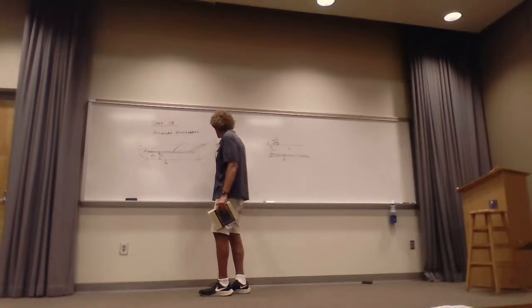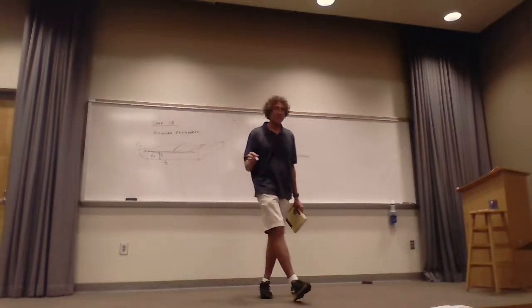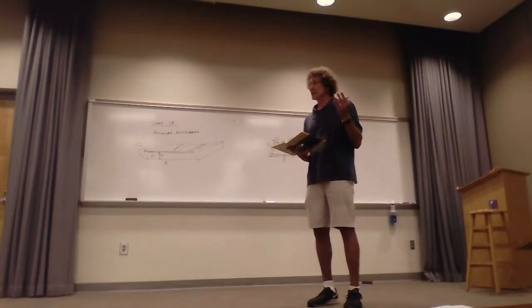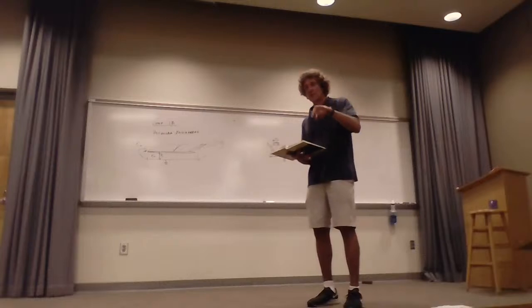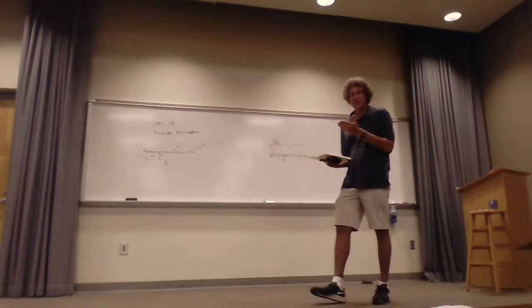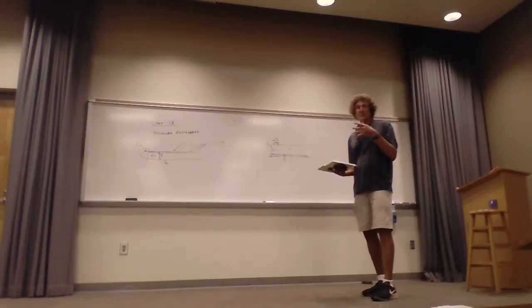As it gets closer and closer to that edge, it changes. It's called the edge effect. And that becomes significant. The reason you'd like to know that is because when you're doing designs on a board, you have to route lines near that edge parallel with it. It's inevitable. You try to cram as much stuff as you want in it. So what we did is I ran a finite element solution to this stuff. So I solved for the characteristic impedance.